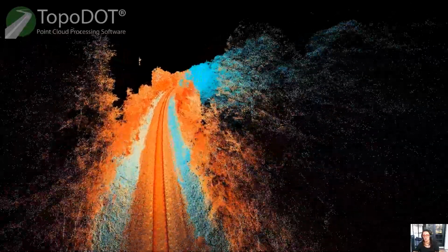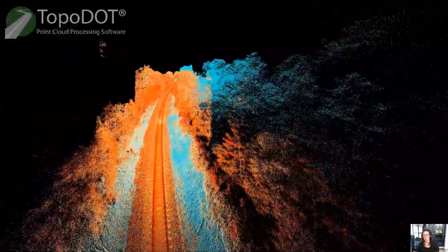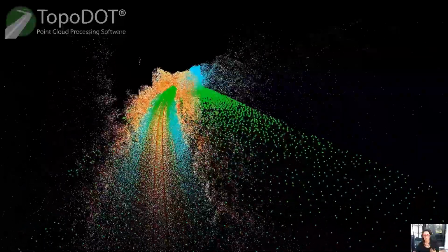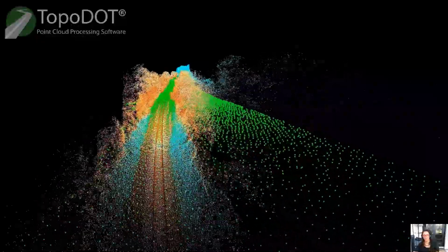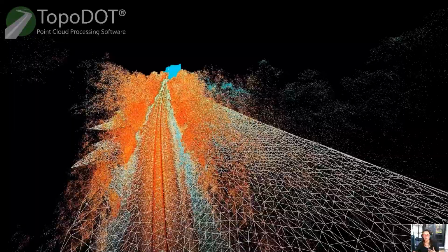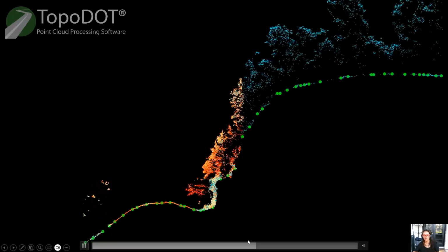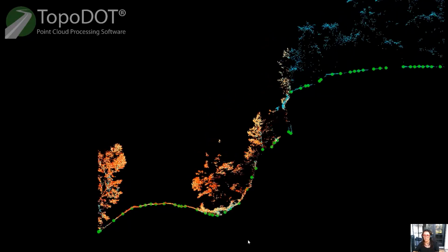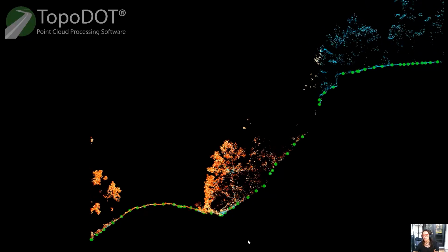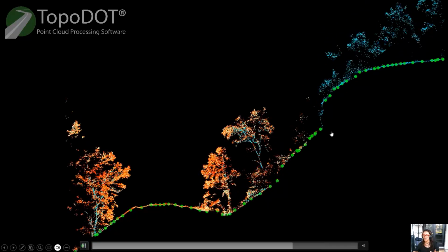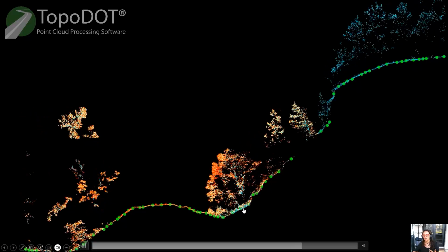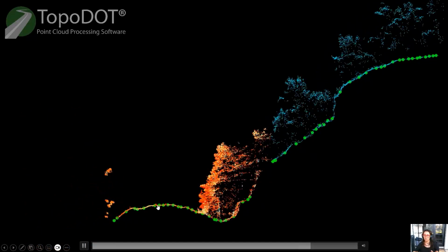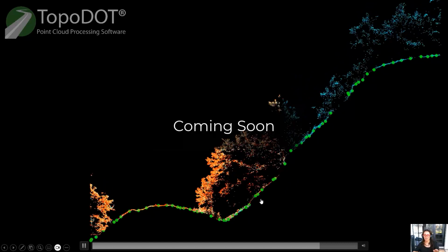Our new ground extraction algorithm focuses on validating points a lot more automatically using AI. And therefore, you're not going to have so much cleanup. You're not going to need to qualify so much the process, but just identify the correct settings and run it. As you can see, it's going to be very easy to create surfaces from these points, even on the rockiest terrain, ignoring all the vegetation and being able to extract just the surface in seconds.